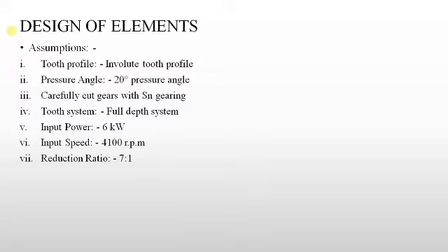Tooth profile: involute tooth profile, pressure angle is equal to 20 degrees. We are using carefully cut gears with SN gearing. Tooth system: full depth system. Input power is 6 kW. Input speed is 4100 rpm and reduction ratio is 7:1.